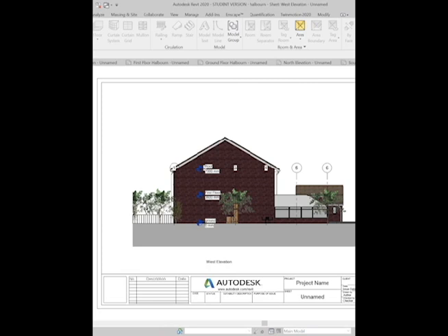So what I need to do really is, well, basically start again, because when I've gone in and scaled the floor plans, I thought I'd done it correctly, but what I'd done is I'd put the floor plans down first, and then I've traced over them with the walls to get the shape of the building, the shape of the rooms. In hindsight, and knowing a little bit more now, I will take the room measurements and build directly just to the measurements. So I wouldn't put the floor plan down as an underlay. I'd work it all out, which you'll be able to see when I rebuild this property.